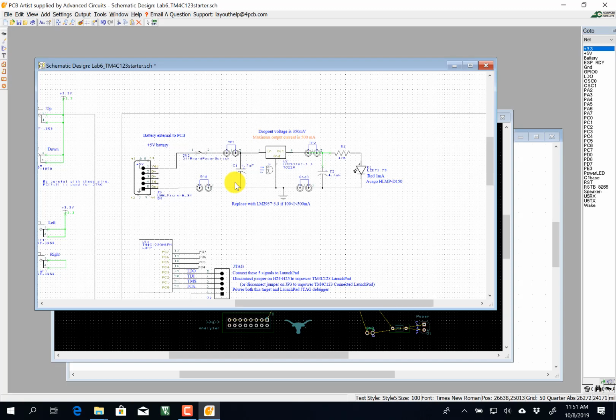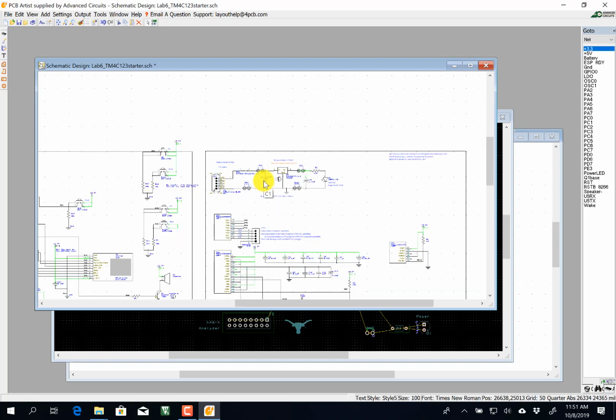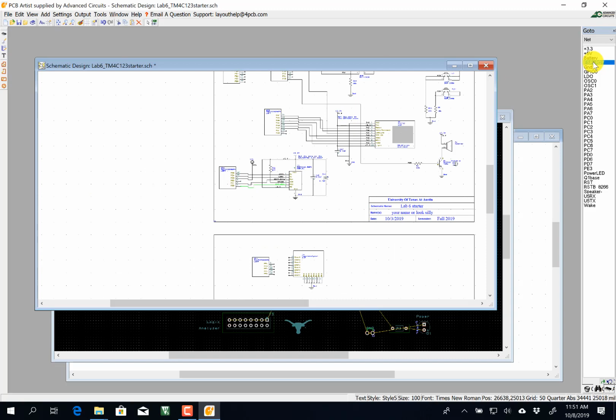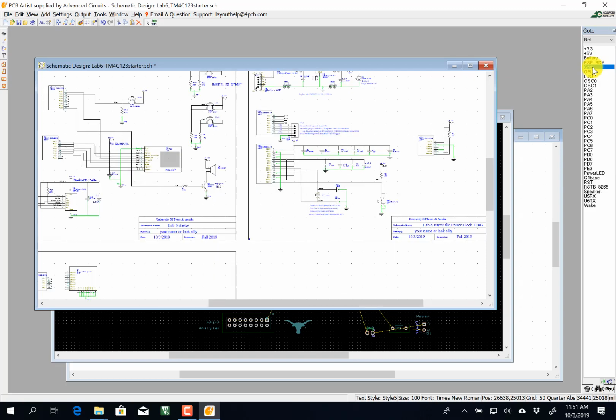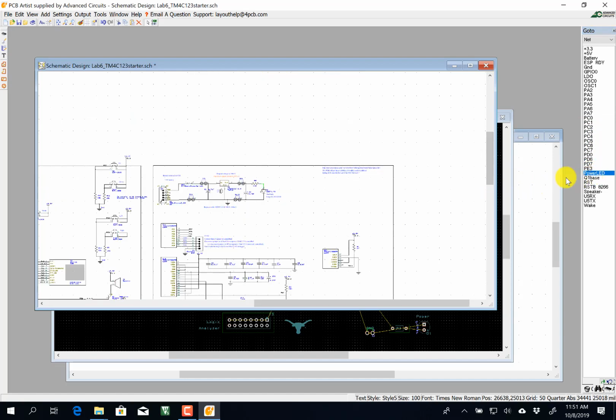All right. So the next step would be to go to my nets and make sure all my nets are proper. You see that I would check them one by one. I would go down and make sure I have a single ground. All the grounds are connected. I have a single one for each of these. I want to make sure that they are properly wired, because if they're not done correctly here, it won't work.